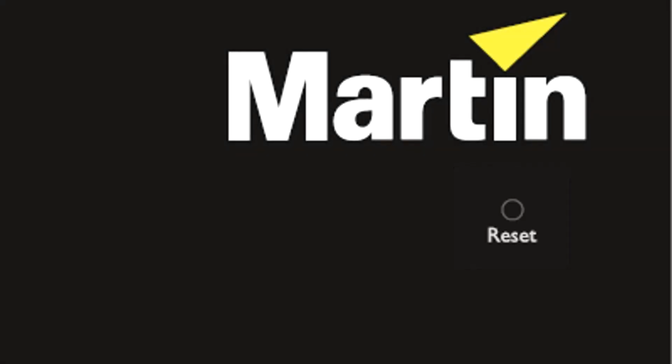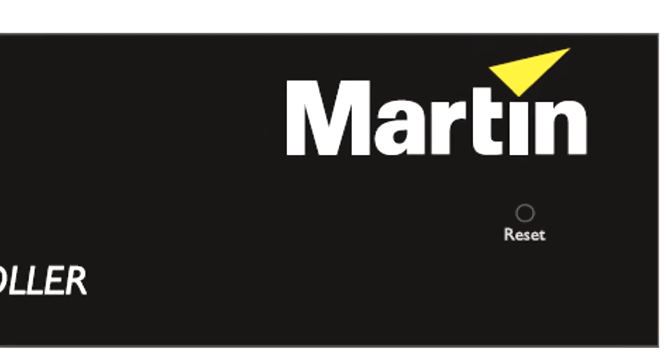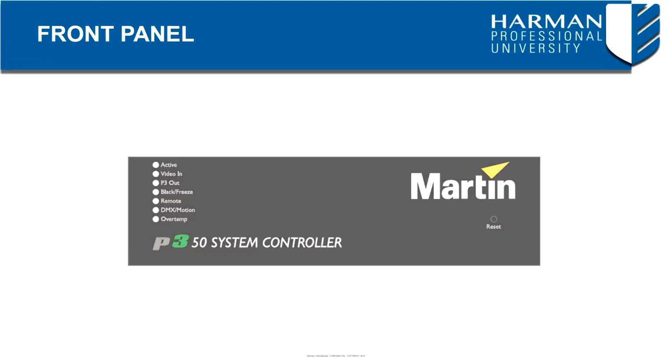The reset button lets you carry out a forced reset if the system controller's P3 application freezes and you cannot reboot the processor normally. Use the tip of a ballpoint pen to push the button. Take note, the system controller constantly stores data in its onboard flash memory, so you are highly unlikely to lose any data if the application fails.